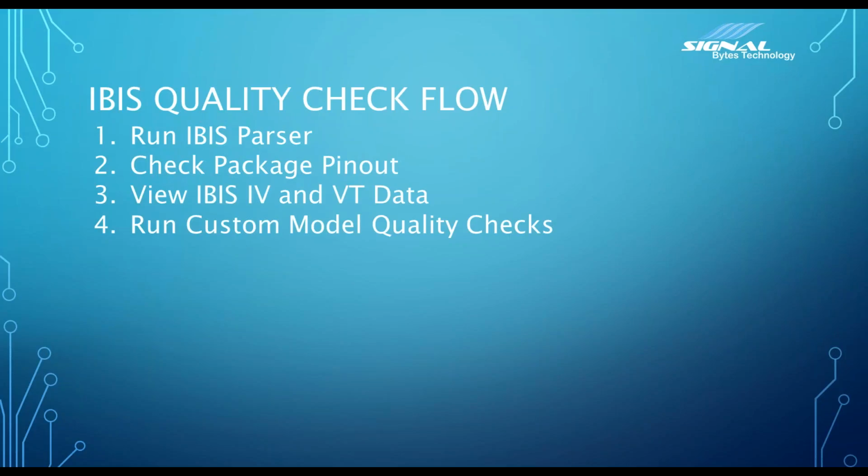That's the idea: to bring in extra stuff that the IBIS checker doesn't do, add in a bunch of stuff that you can get from the IC data sheet, and then you can have much higher confidence that your IBIS model is going to be good.